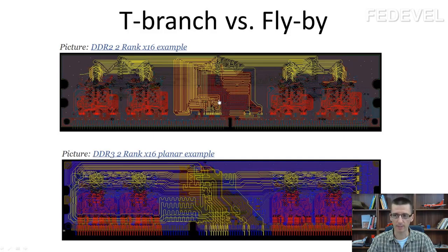It is very important because schematic for these two, it is almost exactly same. If you think about it, these pins, they are connected to all these memories which are here. It's exactly same here. Schematic for this and this is almost same. These pins which are here are also connected to all these memory chips, but they are routed different way. It's important how you draw these tracks.